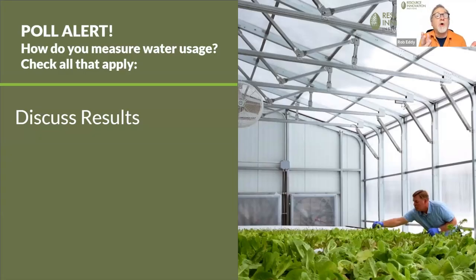Yeah, and so when you talk to these water experts, there'll be some solutions they have for you. Jeff mentioned this, that they're point control. They control right then and there, like UV light. Great system, works really well, but there's no residual. It doesn't go downstream and kill anything. So you can't rely on just a point treatment. You've got to have a combination of point treatments and then something with a residual treatment. There are several things that control biofilm, ozone being one of them.